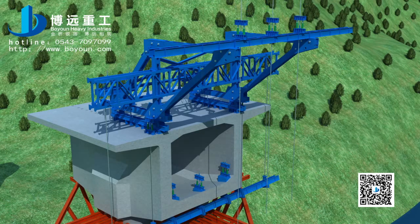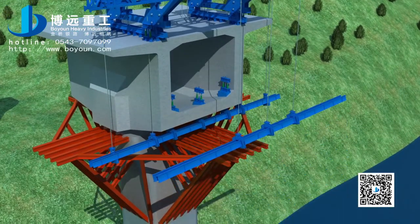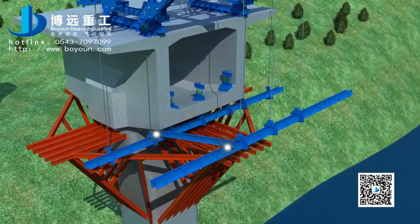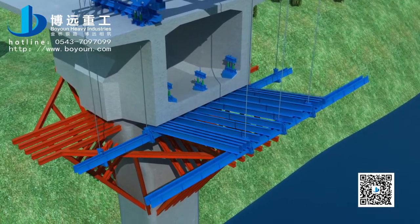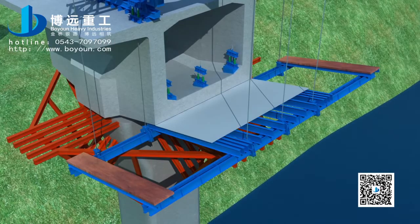Lift the front joist and fix it on the front upper cross girder through the hanging system. Install the bottom longitudinal girder according to the space, specification, and route number of the forming traveler installation drawing to weld on the front and rear joist. Then, install the bottom framework and walking platform.